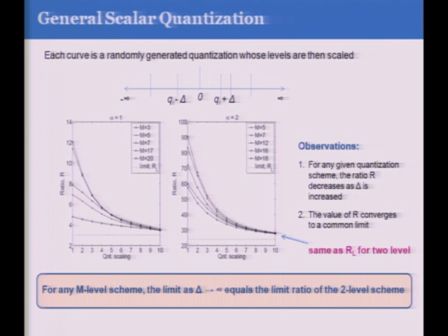The idea is that if you scale the center one, you need a much longer sequence to compress it down to the size of the key. So if you want, let's say, a 128-bit key, you might need a much longer stream of Y's, received symbols, if you went through this quantization. But the hope is that the amount of reconciliation also decreases. This is the general case of the specific case of binary, because you get the maximum information per bit in a noisy environment with a two-level system. That's why you don't have three-state computers.